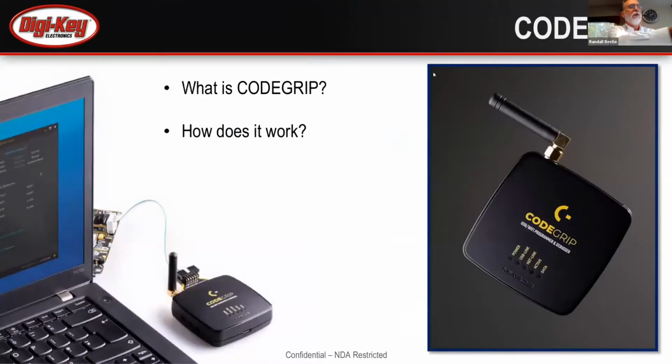I'm not sure, I think you can probably see my video. I have in my hands one of the units that's on the screen. This is an in-circuit debugger, and it has a little adapter board that adapts to a wide variety of microprocessors. It depends on this adapter cable, and then what you're able to do with this end is plug it into your target board. This has access to your integrated development environment on your PC via a USB connection. But what's really unique with this is it also happens to have a Wi-Fi connection. And this has all been available in the last year or so.